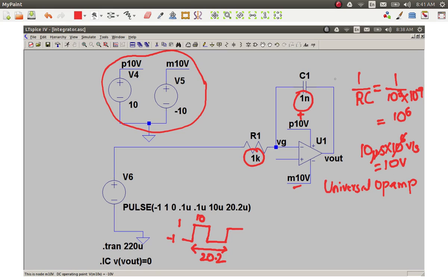So this was slope. And this is what should happen in a period. So this is actually t divided by RC, and this is the final value of that. How much would this change over the period when it is on, over the on time, would be this. That's what we have done here. So it should change 10 volts from top to bottom, bottom to top. So this should be around 10 volts.